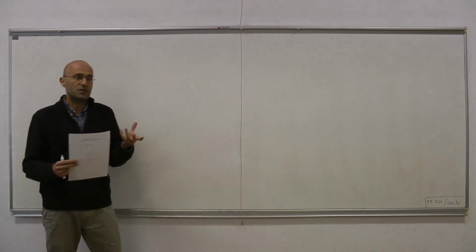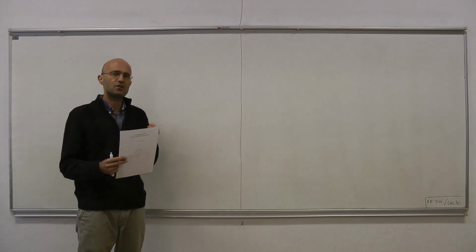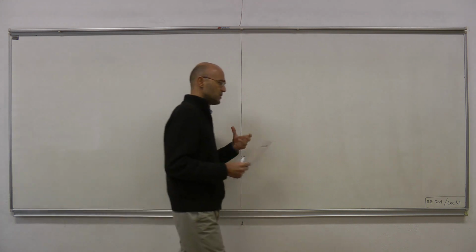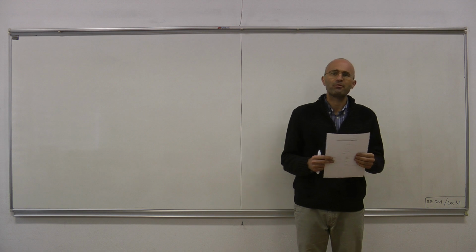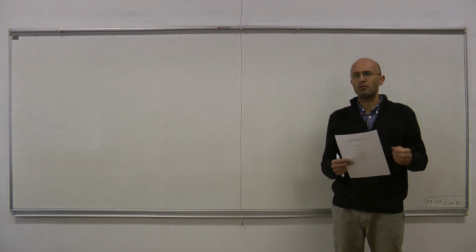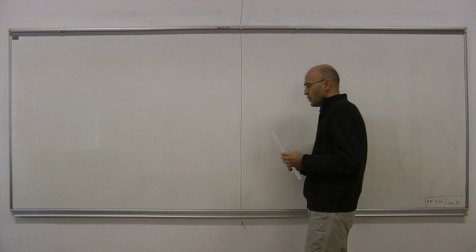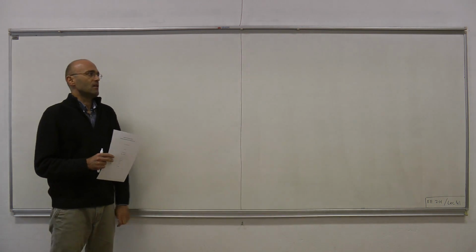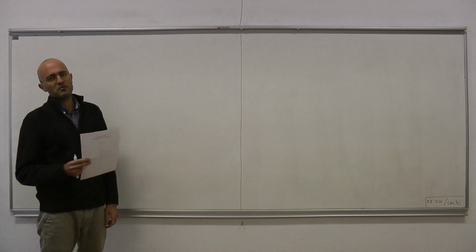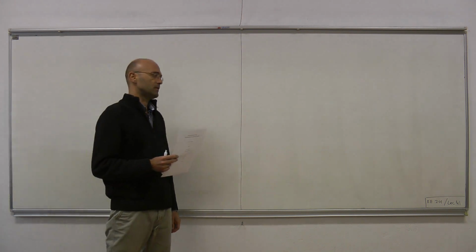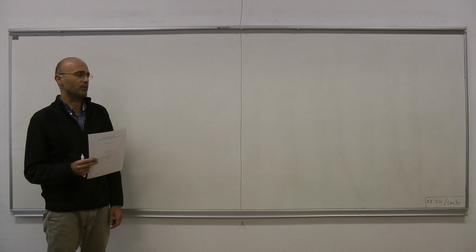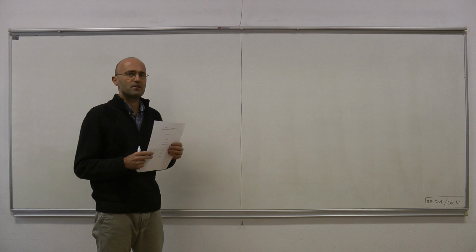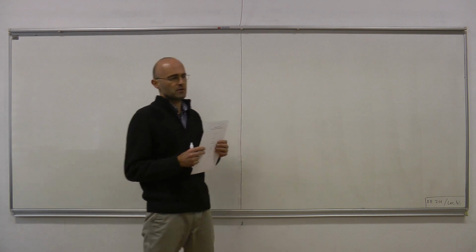Therefore, in a sense, the impulse response contains all the information, or it's a complete characterization of the circuit from the input-output point of view. Also, we will see in 202, not in 201, that the impulse response is very closely related to the concept of the transfer function. Therefore, it's worthwhile to spend some time on impulse response.